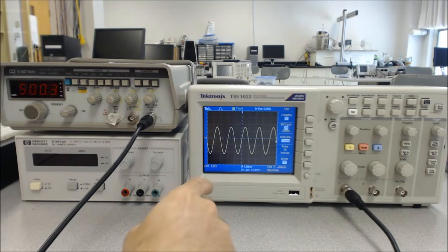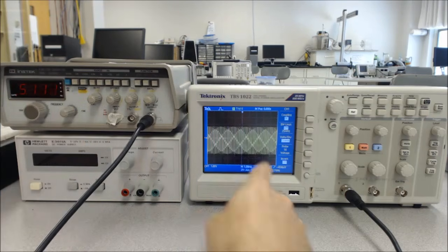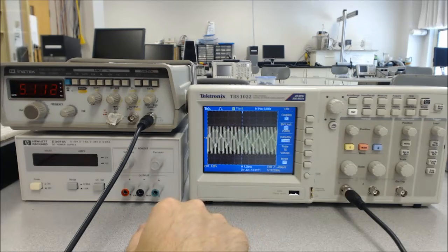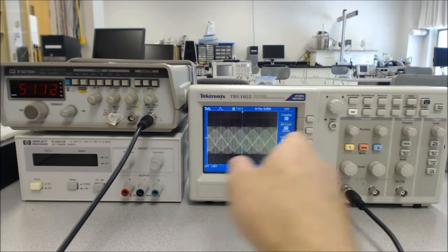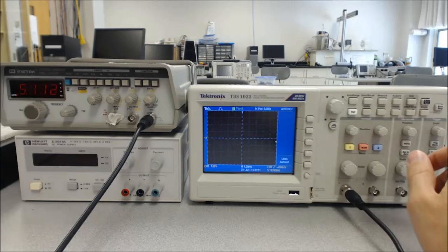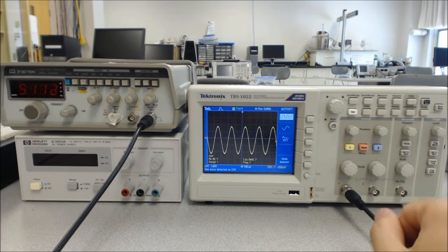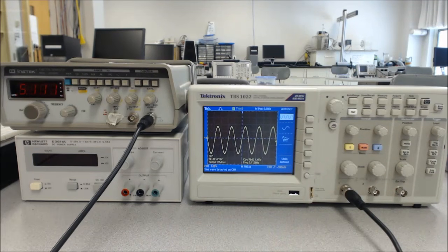So I was using this before, but most of the time when you turn on your oscilloscope and hook it up to the function generator, you'll get something on the screen that doesn't look a whole lot like anything. And if that happens, I'm going to show you the most useful button on the oscilloscope first, which is the auto set button. Your oscilloscope may look slightly different than this, but it should have basically the same type of functionality. So you push that button and magically the sine wave that you're looking for appears on the screen and everything looks great. So definitely remember the auto set button if you get yourself in trouble.